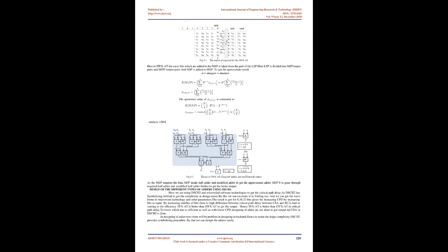A equals full-width adder tree, FL-AT, and fixed-width adder tree, FX-AT. A scheme to develop an efficient FX-AT design with truncated input. Use of truncated input in FXAT offers two-fold advantages. 1. Area and delay saving within the FXAT due to reduction in adder width by p bits, and 2. It creates scope to optimize other computing blocks that appear upstream of it in a complex design.